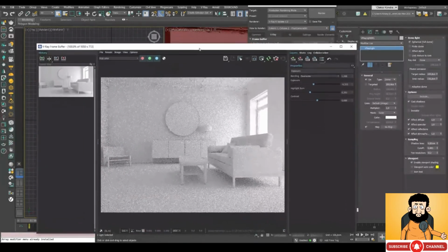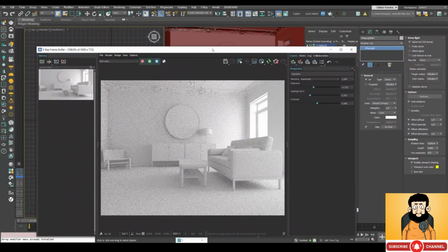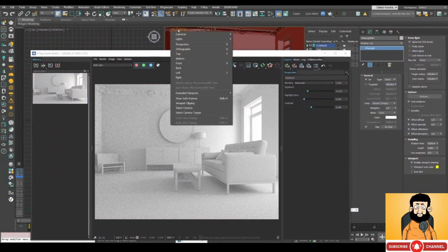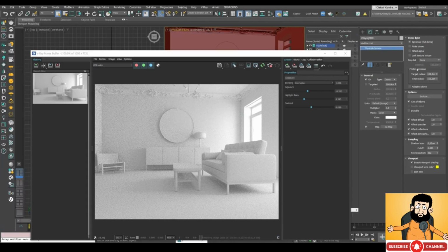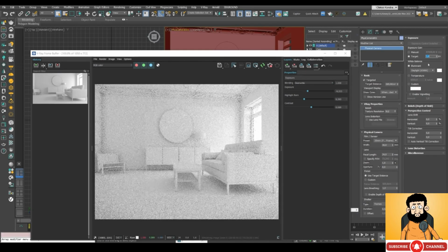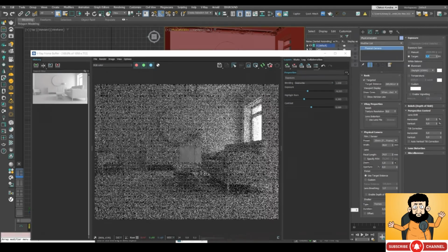It's very important. All right, so we turn V-Ray Dome back on, and now we need to adjust exposure in the camera settings. We're using physical camera. You can use V-Ray camera, it doesn't matter. So we click Select Camera. In the exposure tab, there's a parameter called target. It's currently at 4, we'll make it 3. Actually, let's try 6.